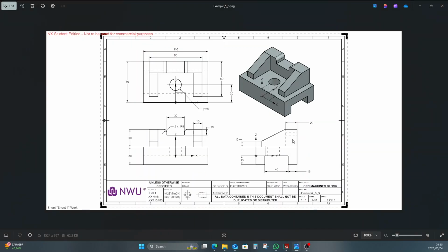Okay, so now we can add that feature on top. So I'm going to start by creating that part there. That's a rectangular shape extruded along that way with a length of 90 millimeters, meaning that that distance there and there adds up to 20 to get to 110, meaning that should be 10 and that should be 10.